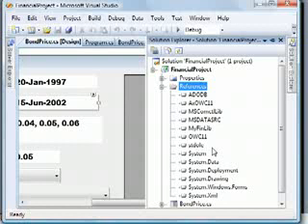We also need the MWArray assembly, which converts the C# data type to a MATLAB understandable format. In MATLAB, all the data types are considered to be a matrix. For example, if we enter a string, it is considered to be a one-dimensional array of characters. So we need a similar thing in our project.